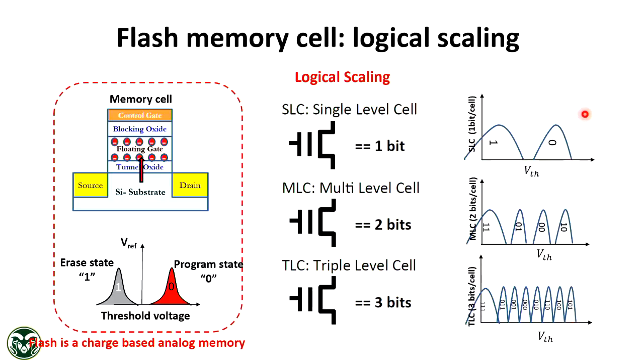The highest VT level and lowest VT level, which is around 0, so that range is pretty much fixed. That means the challenge for multi-bit levels is you have to narrow the distribution as much as possible. Because one distribution superimposing with another will cause error, because then you cannot distinguish which level it is.